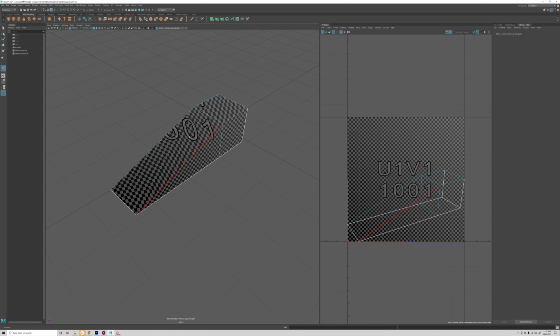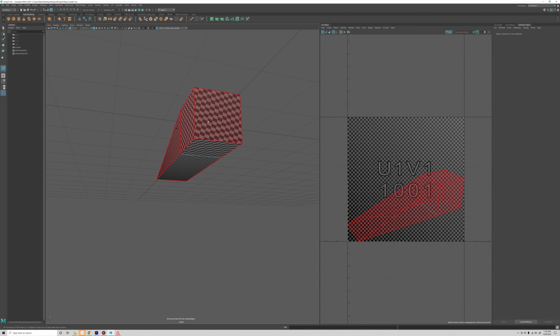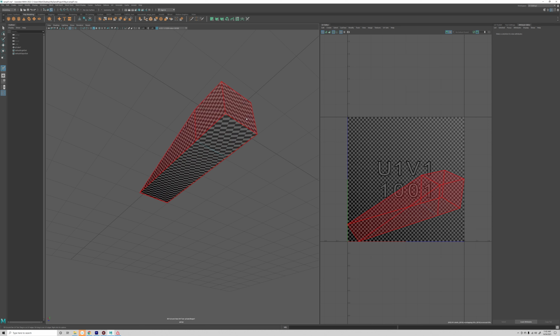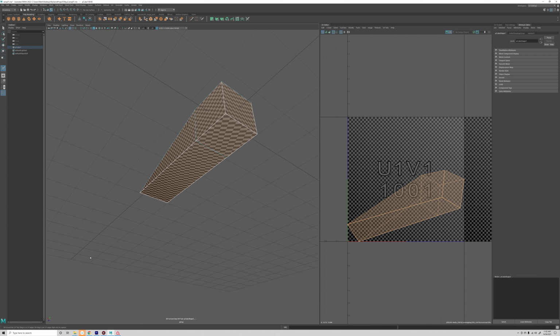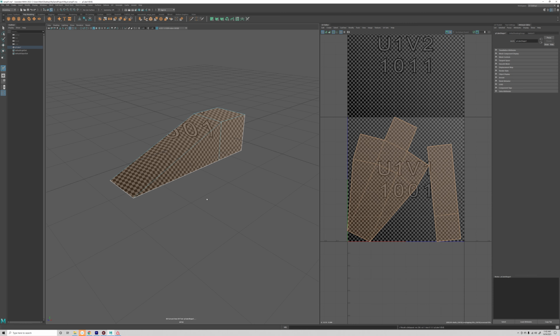What I need to do here is hold down the right mouse, Component, UV Shell. I need to be in UV shell mode, and I need to select every UV shell. Because there's only one UV shell in this model, no, there's two, because I've cut out the whole base. So instead of selecting them like this, I want to drag over to make sure I get the entire model, so everything is selected, and I press D, the last letter of unfold. It thinks for a second, and because it's such a simple model, it doesn't think for very long, and it unwraps it, it unfolds it.